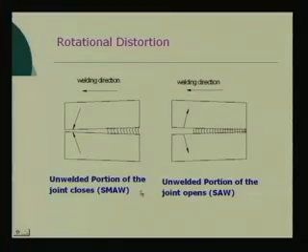So, that closing takes place when you are welding with a method whose welding speed is slow. That means, if say two plates 10 meter long are there, and you are welding with a manual method, shielded metal arc welding, as you cross almost half of the plate, you will gradually find that the gap is becoming less and less, and beyond half the length, that means 5 meters is over, you won't be able to proceed any further because they are touching.